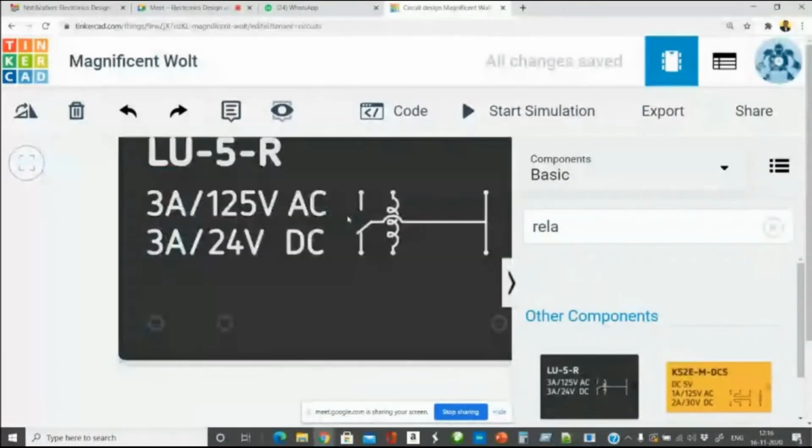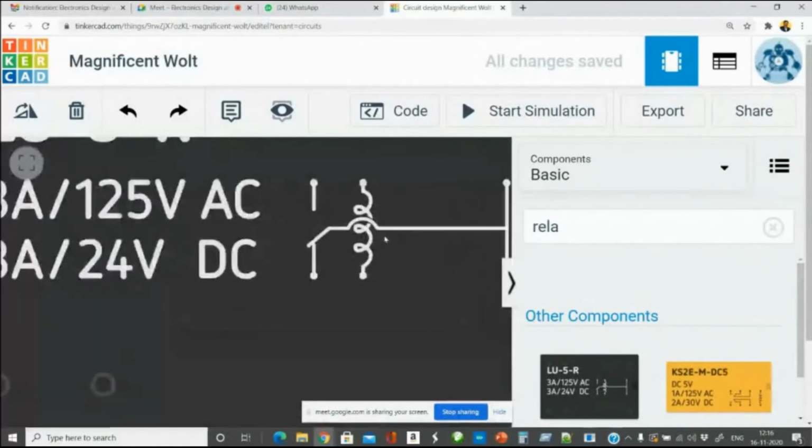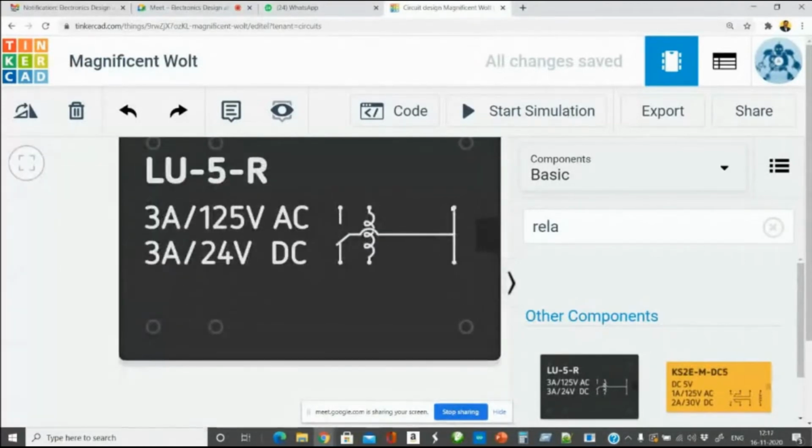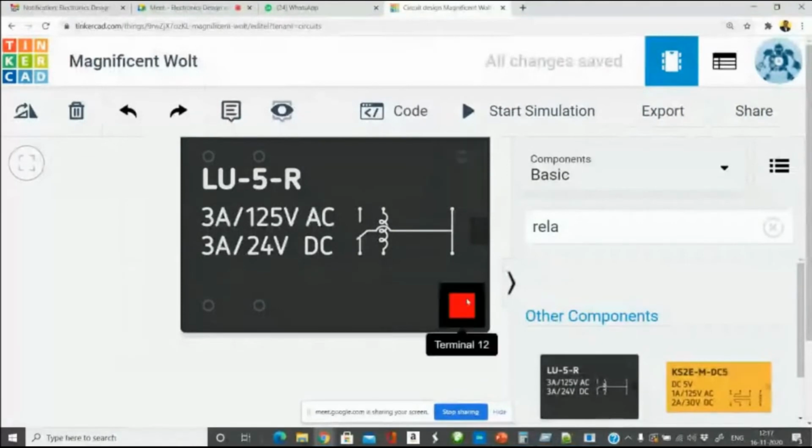So if you see the schematic diagram of the relay, our conventional relays have 5 terminals. Here this fellow has 6 terminals. If you understand this diagram, you can understand. So this is my common terminal. Instead of one common terminal, you have 2 common terminals. Both of them are short circuited. You can either take the connection here or here. Both are one and the same.